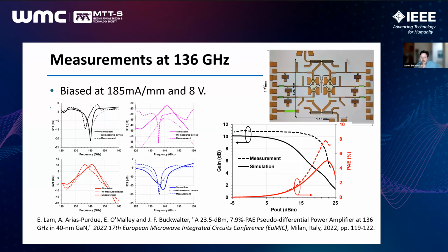The results here gave us something in line with our gain under small signal conditions. We ended up measuring a bit better PAE. This reached about 8%. Again, the higher power density is helpful because we expected with the differential device to get around 22 dBm, 21 to 22 dBm per side. We got a total combined power of 23.5 dBm under this maximum PSAT.